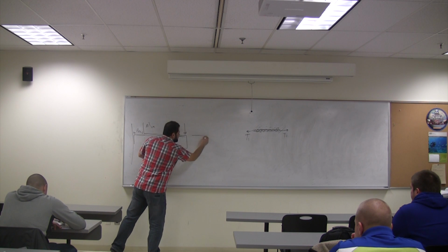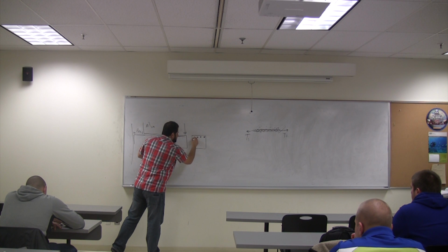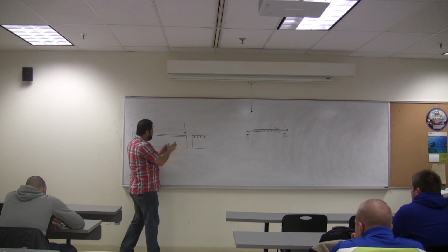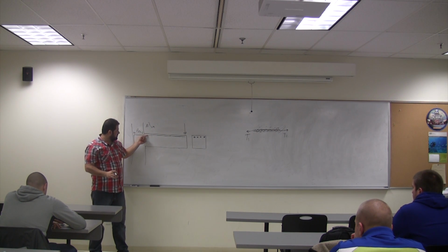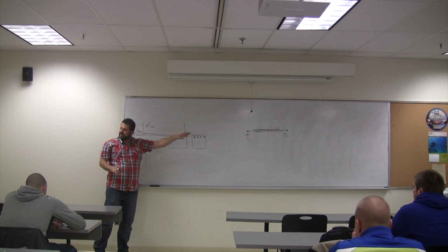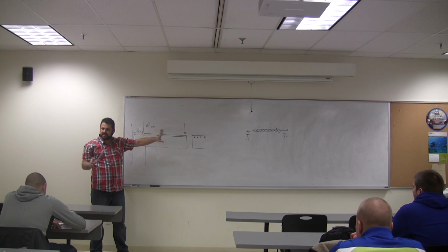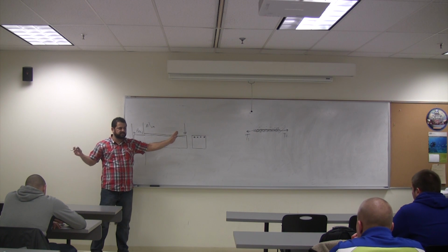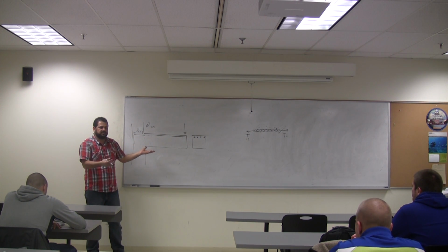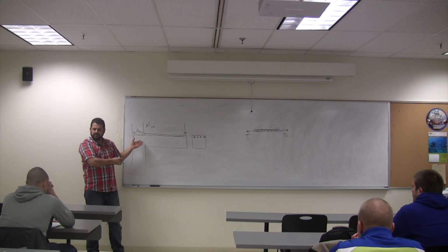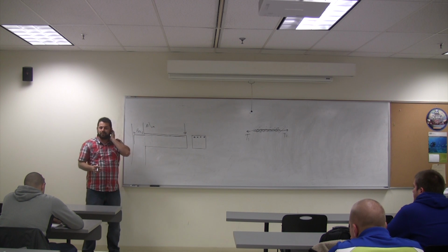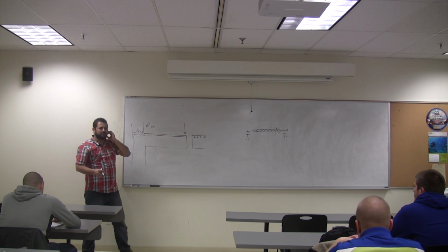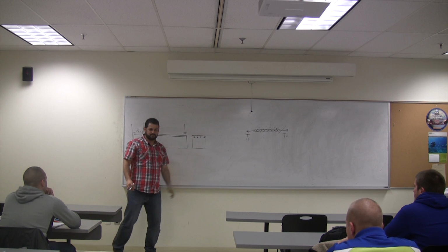Okay, look. If our design called for 4 bars, everybody, if we require 4 bars for this cantilever, number 7, number 8, whatever, 4 bars. That's what the design called for. After we finish flexural design, because when do we check the development length? After everything, right? So you have 4 bars. Now tell me where is the location where I can stop the 2 middle ones.